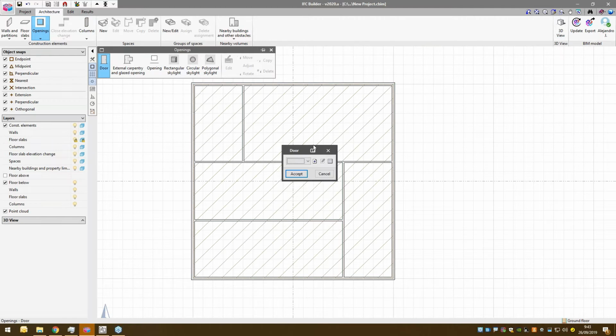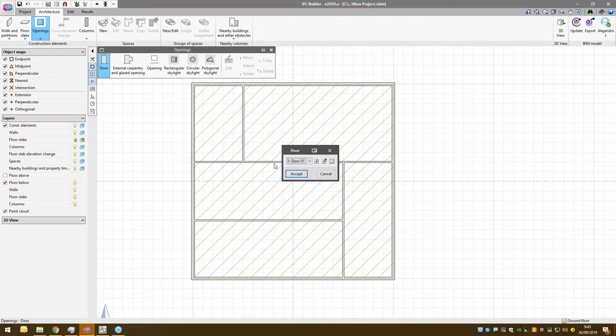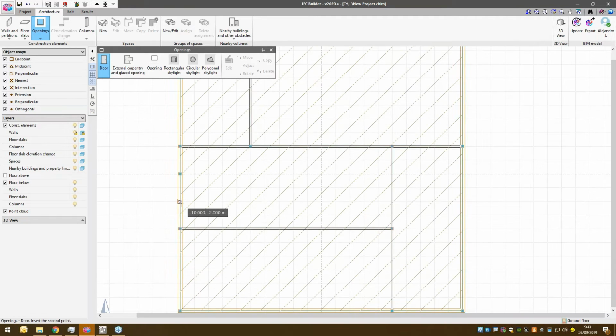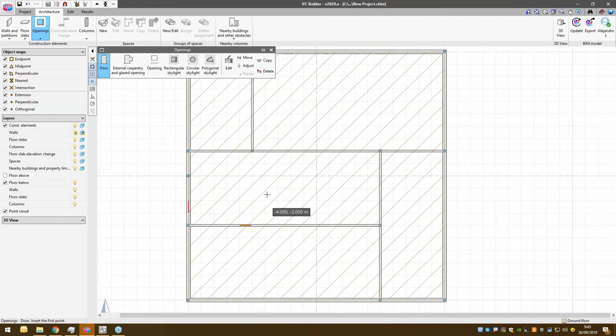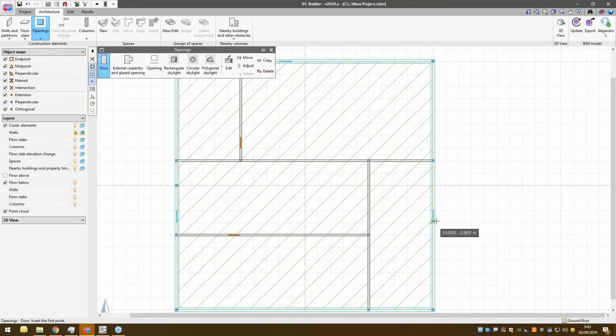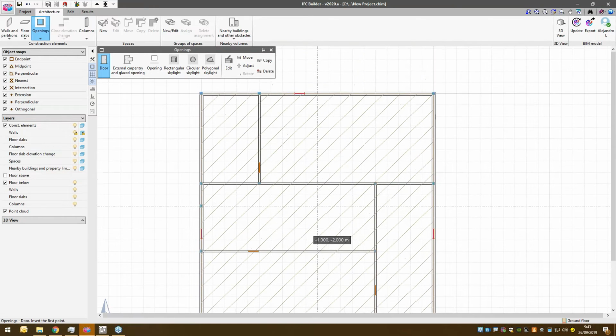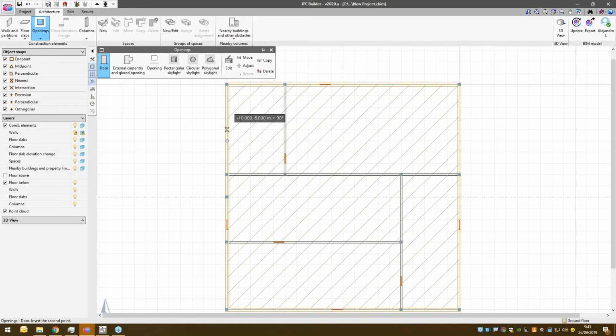If we jump into the next tab, you're going to find different tools for drawing several kinds of openings, starting from doors. For example, door 1, width 90 centimeters, height 230. Okay. And you can just start drawing. Right now, I'm snapping to the grid. You could also do free drawing or use external snaps. I'm just gonna stay with this in order to draw quicker.